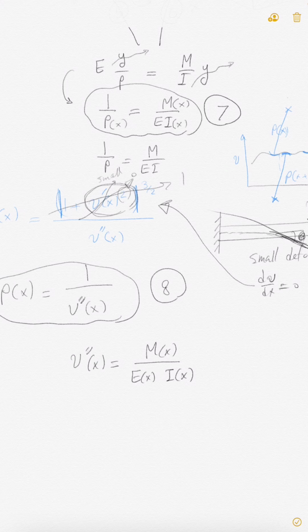It's very important, measured with respect to the centroid. Now usually, because you have x everywhere, they simplify it. They write the second derivative is equal to M over EI. This makes the equation compact, right? The notation is simplified. Now this is the final thing I need to compute my deflection.